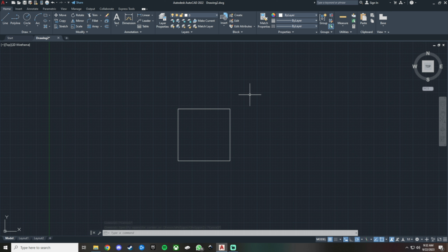The next way is by creating a green block, and the way we're going to do that is also left click, but don't hold it in, just left click and let go, and we're going to start moving to the left hand side of our screen, and we have now created this green dotted block. With this green dotted block, it selects the item even though it's not completely inside of the block. Let me quickly show you what I mean. If I hover over these two lines, it has already selected them, even though the lines are still outside of the block.